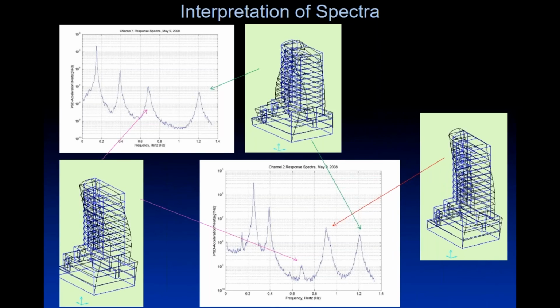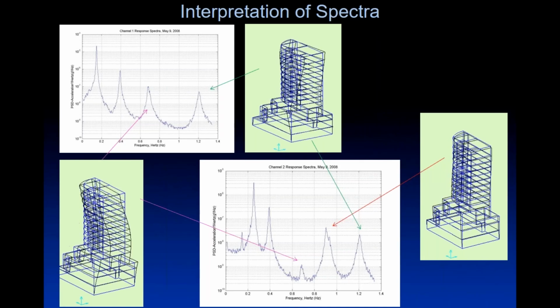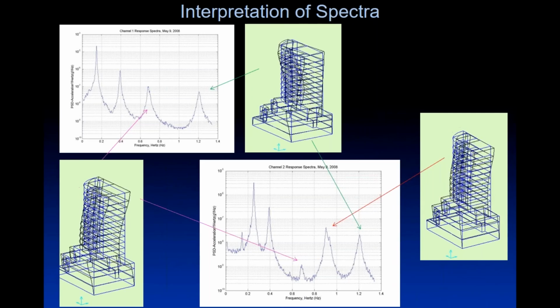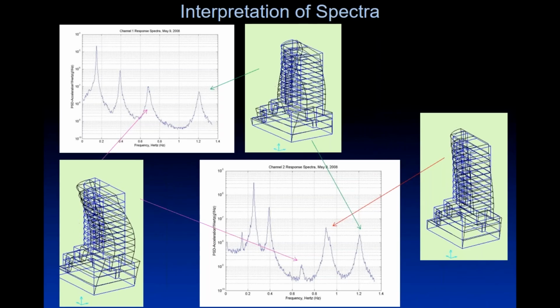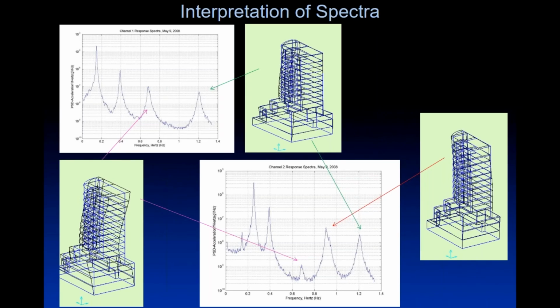This actually says to us that the information carried by these different modes of vibration are different because they're sensitive to how much motion there is going on. If we've got more motion going on in the foundations here, we've got more information about that motion coming from that higher frequency mode of vibration. We can reverse engineer this.